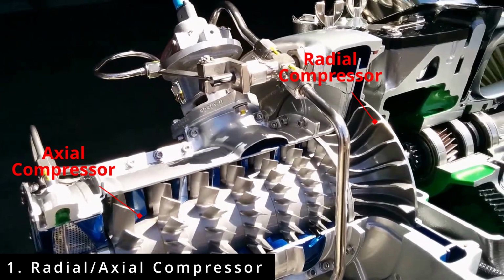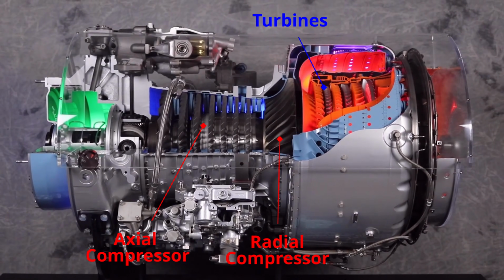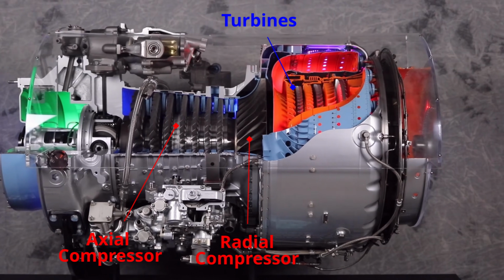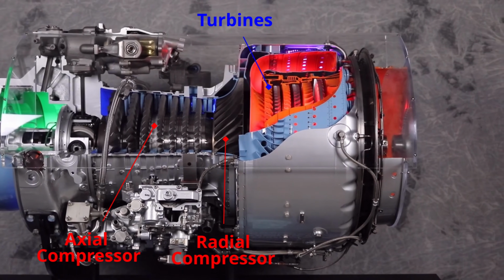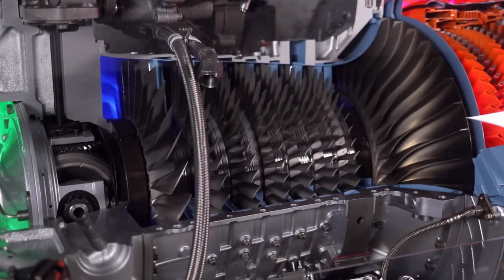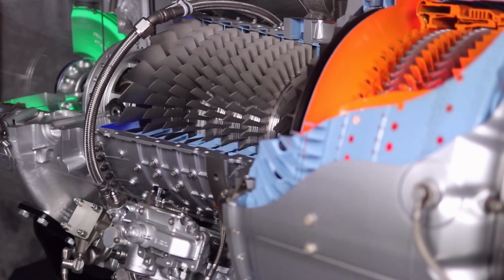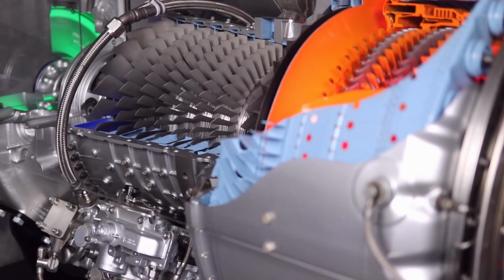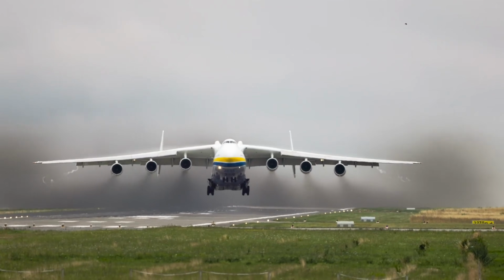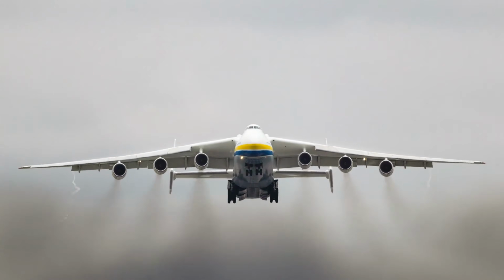By stacking multiple compressors together, also known as stages, you can create a good pressure ratio and significantly reduce engine diameter. This is important, since aerodynamics dictates that airframe structures be thin and sleek. The majority of large engines you see on commercial aircraft use axial compressors.